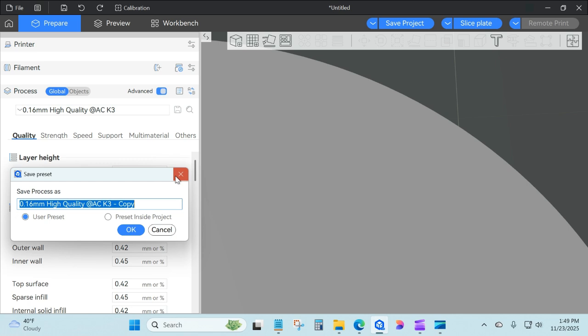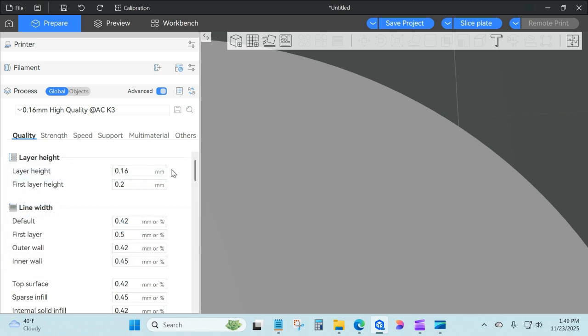All right, back to our fields. Okay, so layer height we talked about. We didn't talk about why it is so important. A little bit, I did talk about surface damage and quality, right? So the higher your layer height, the less quality you'll have visually on your model. From a sloped surface looking at it, it will have either some chunky lines or some smooth surface depending on what you enter in here.